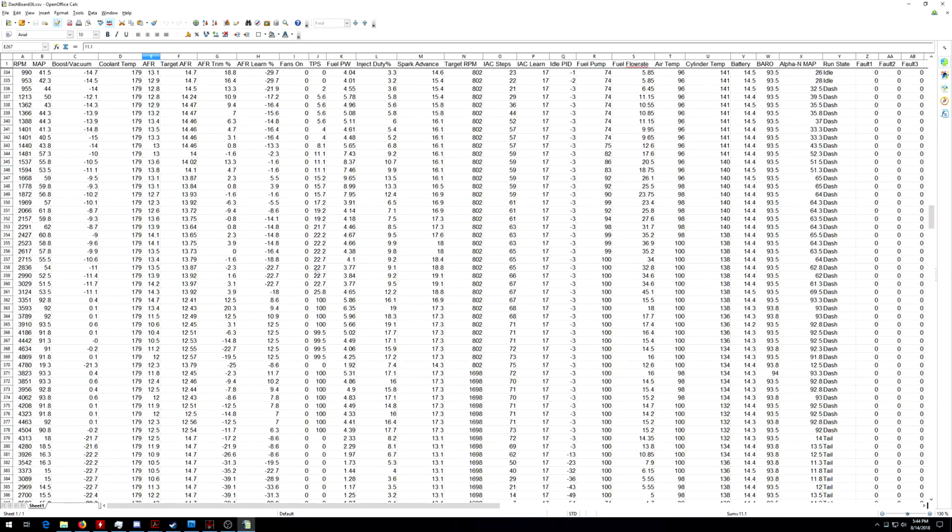Now this is the second hit that I did. You can see I rolled into it in second gear, mashed the gas. This time it did show 100% throttle. Again, it went a bit lean, and then it tried to dump a bunch of fuel in, and back to a rich condition, all the way to 10.4 to 1 AFRs.